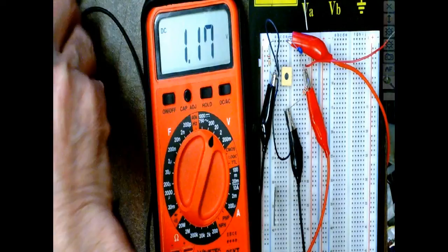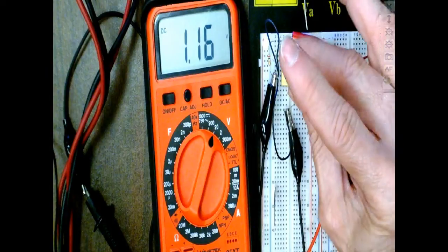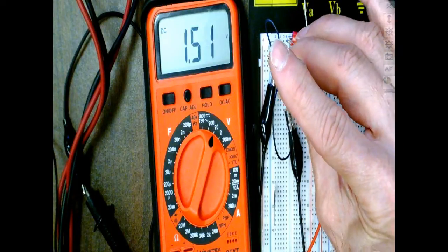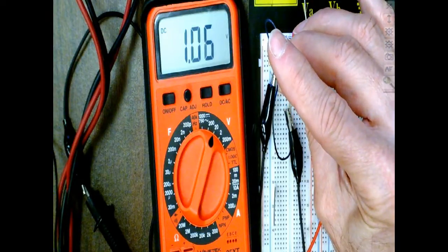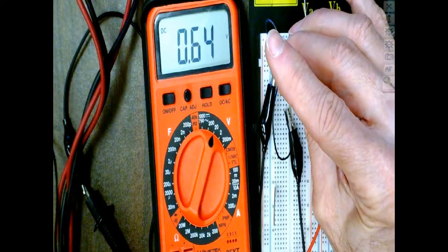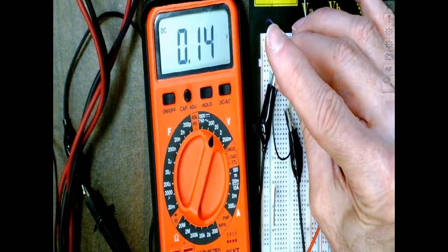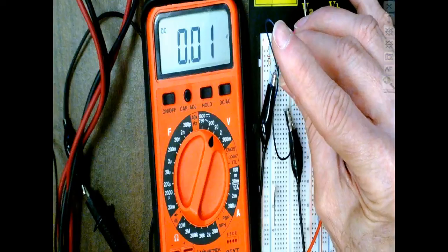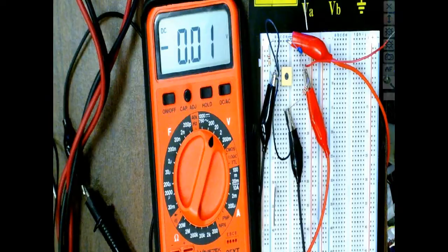So what I can do now is I can come over here on my potentiometer, and I can adjust this to balance the bridge, wrong way, Rich, and I'll adjust it till I get 0 volts. Now, as soon as I get 0 volts, and this is the big advantage of a Wheatstone bridge right here, is that we can use a Wheatstone bridge to set a 0 reference. Okay. So now I've got a 0 reference set.